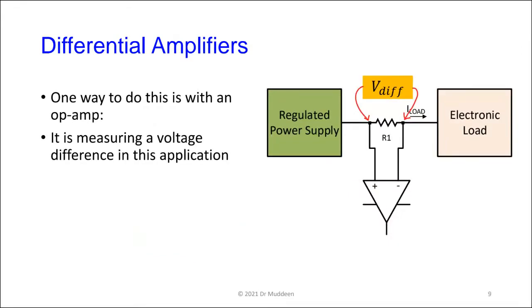And you encounter that, in fact, in some other applications, like in medical applications, when they put electrodes on the body to measure, for instance, the heart's electrical signals. Your body itself, because we are in an atmosphere with a lot of electromagnetic radiation from, for instance, the power supplies in the wall, has a 60 hertz signal that acts like an antenna, and that is there all the time. It's a very, very low power, but if you have ever held an oscilloscope probe in your hand and watched your oscilloscope display, as you squeeze the probe with your fingers, you're going to see a 60 hertz signal appear on the screen.